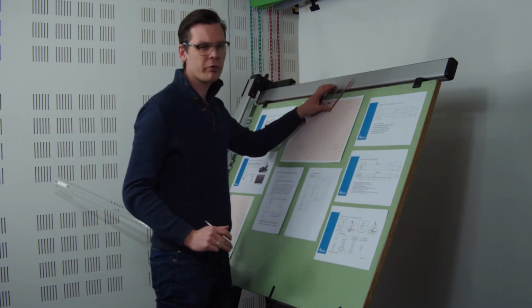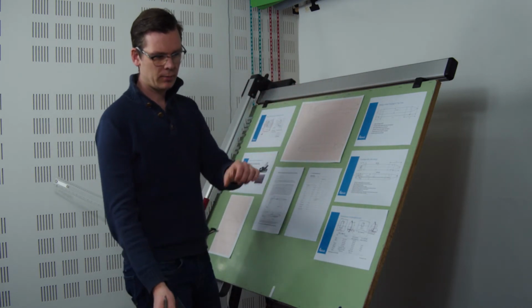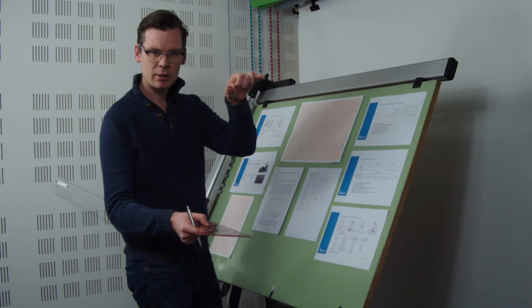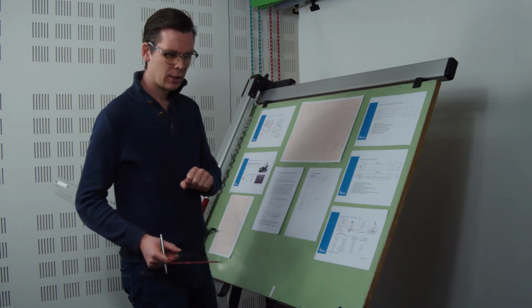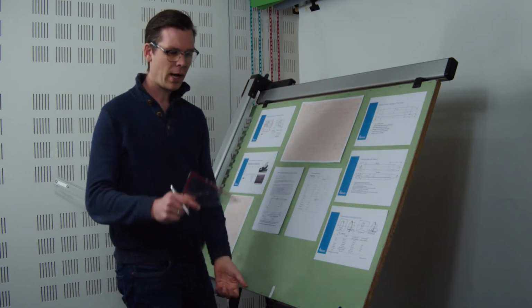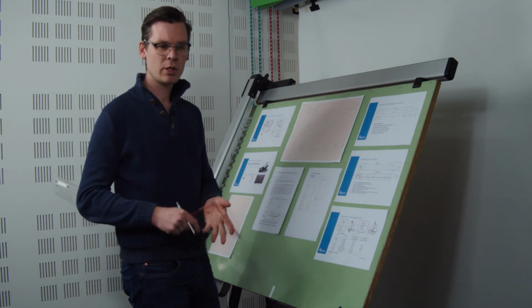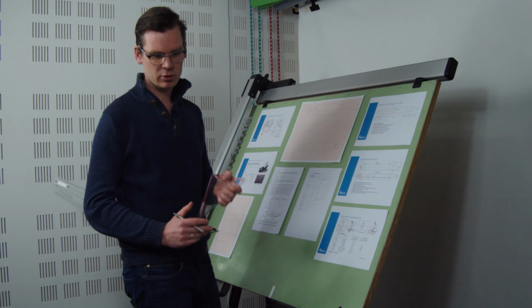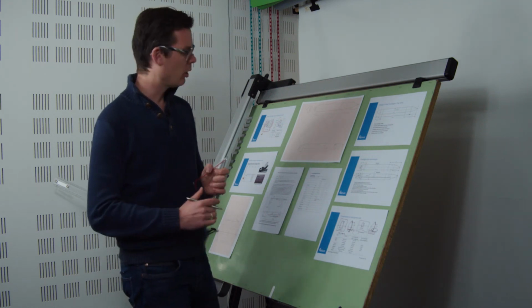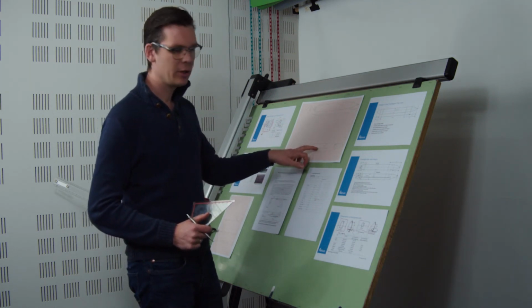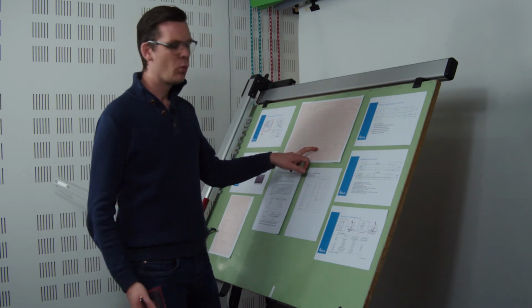And this is an over the wing exit, so I'm positioning this thing a little bit higher such that it's easy to go out. And there are some regulations that state how high you can position it such that you can still step out easily out of the fuselage and then step onto the wing. So there's also a distance between the lower side of the exit and the wing surface. We don't have a wing yet.